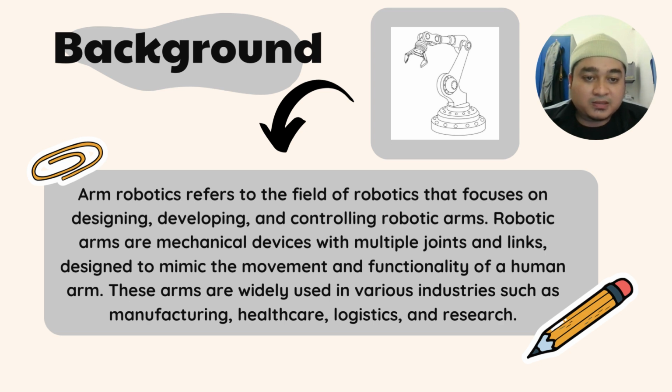To accomplish precise and responsive management of position, velocity, and acceleration, PID control modifies the control signal based on proportional, integral and derivative terms. In closed-loop operation, the control system constantly modifies the control signal in response to position feedback. This enables the robotic arm to adjust flexibly to environmental change or operational disturbance.